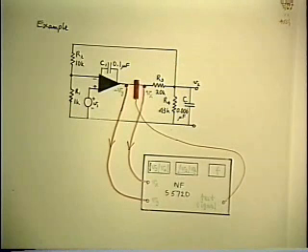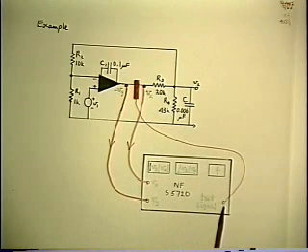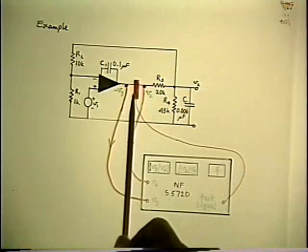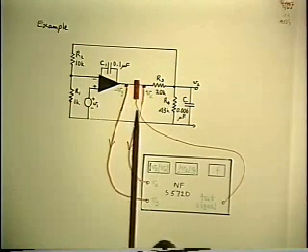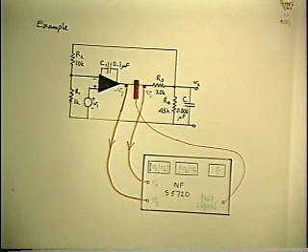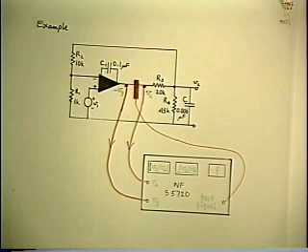But any real transformer works backwards. So what we're doing is plugging the probe into a signal source, and you clip it around the wire, and it works as a one-turn secondary isolation injection transformer. And it injects a voltage into the piece of wire.